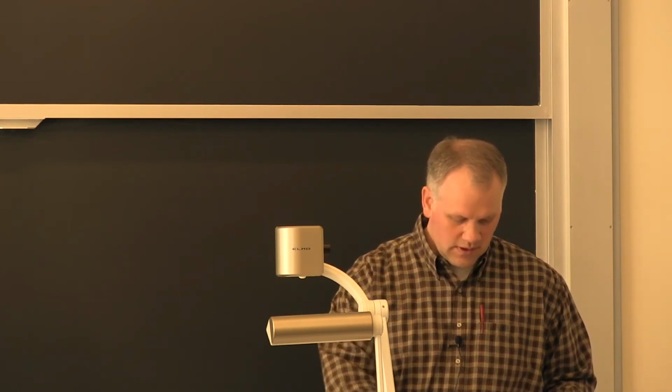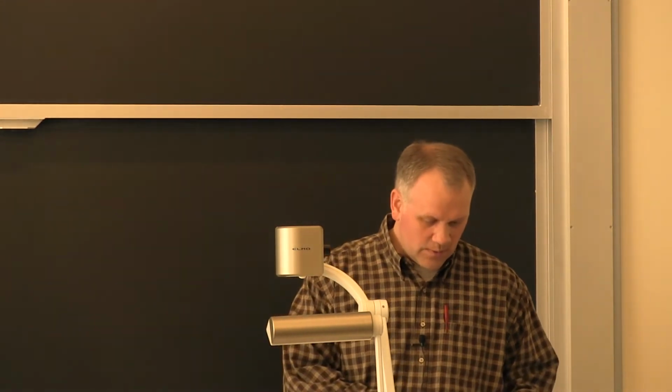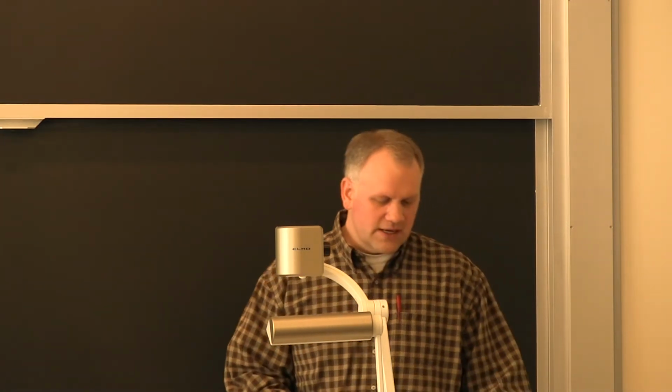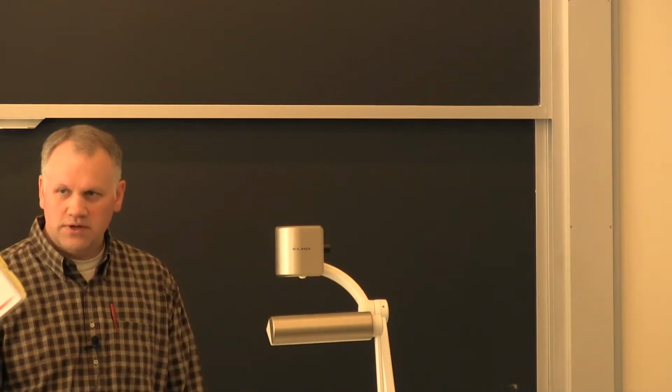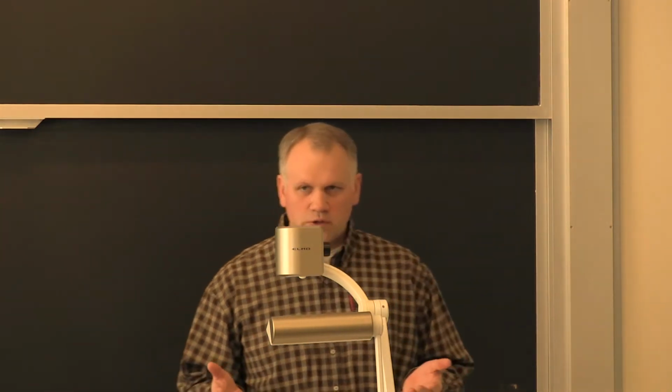So just wanted to say a few words about the different documents that would be used. A code is a body of laws that's arranged systematically for easy reference and use. Easy being put in quotation marks because sometimes the codes are somewhat complicated. But because a code has legal status, it's by definition mandatory. And so an example of a code is the structural welding code that you've probably heard of in this class. It gives the legal rules.